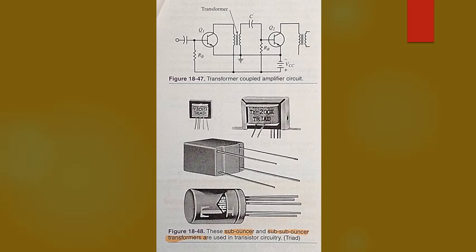The major drawback of transformer coupling, besides the cost, is the poor frequency response of transformers. They tend to saturate at high audio frequencies. At radio frequencies, inductance and winding capacitance present problems.